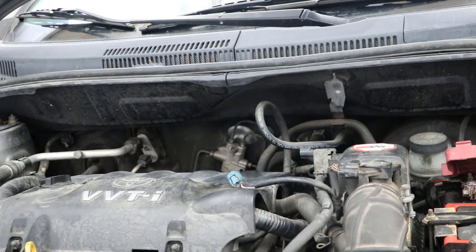I am going to clamp it off with some clamps that I have put a little bit of black tape on, just to make sure I don't dig into the hose, because these are a little bit older hoses and they are cracking, as you can see by one of our problems here. Now, there are super cheap fixes you can do if the customer really doesn't want to spend anything. But I am really going to recommend replacing these hoses, which is very easy and very inexpensive.